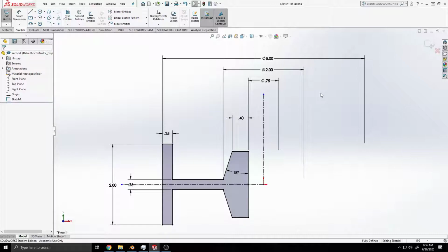All right, we're ready now to revolve this. Now before we revolve it, let's think about what we want to revolve it around. Note we have 2 center lines. Solidworks, if it only detects one center line, will automatically revolve around it. But if you have multiple center lines, it doesn't know which one, and it forces you to select it. So we know we're going to revolve around this vertical center line, so select it. And you could pre-select it. You could also post-select it.